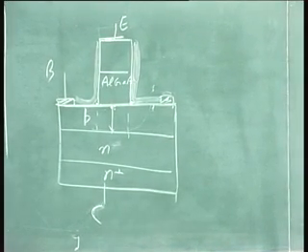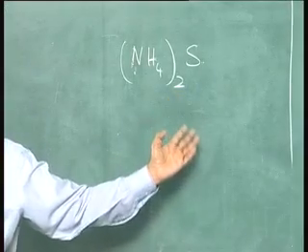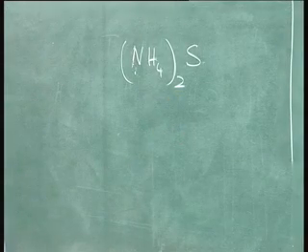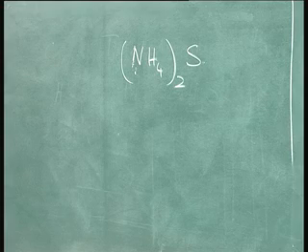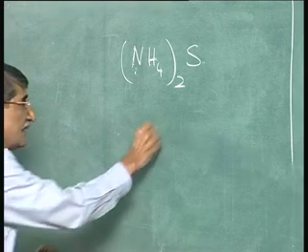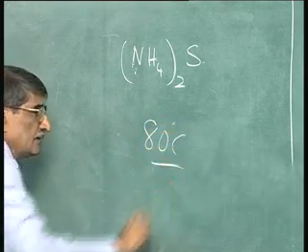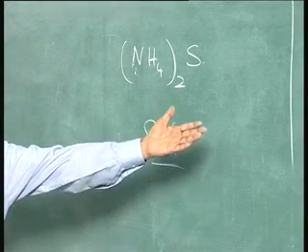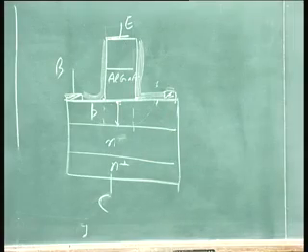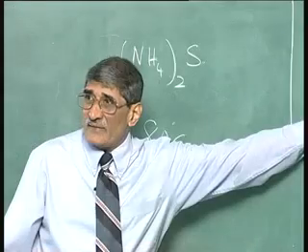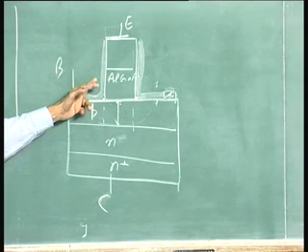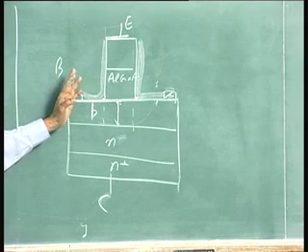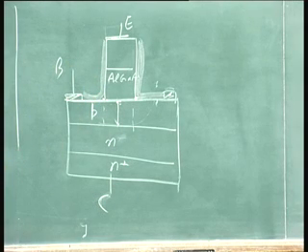okay, because of the sulfur. And this of course you do at about 70-80 degrees centigrade and dip it in the solution, keep it say 15 minutes, 20 minutes at about 80 degrees centigrade. It gives quite a good passivation, no surface leakage, because the junction does not have an ohmic layer on the surface. So, leakage current is low, people made solar cells, okay.